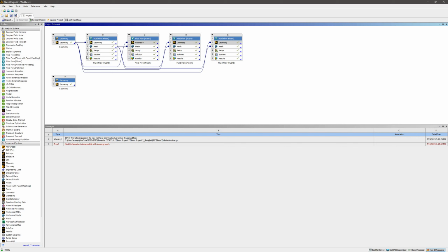But I definitely want to go through the geometry, the mesh setup, and the typical setup for the inviscid simulation, and then the rotating simulation. These two have the same setup as this, and I'm only changing the wall rotational speed. Other than that, it's the exact same. So yeah, that's my Fluent project two.